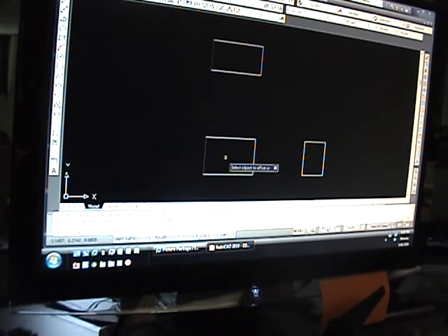I think it's a 1/2 inch. So we can offset 0.5 here to here. You can also offset 0.5 from the bottom here to here, and then we can use the fillet command.